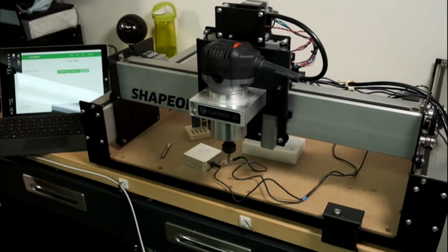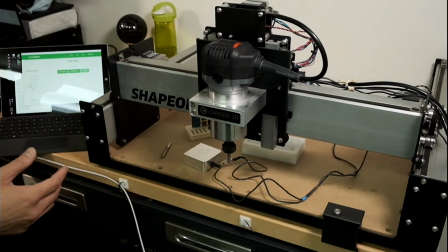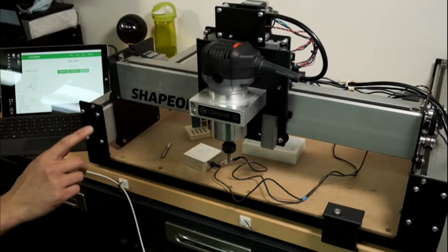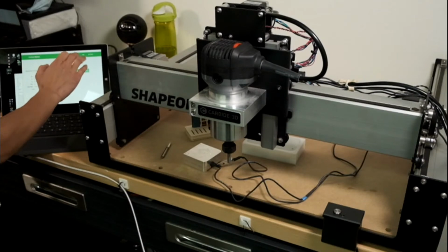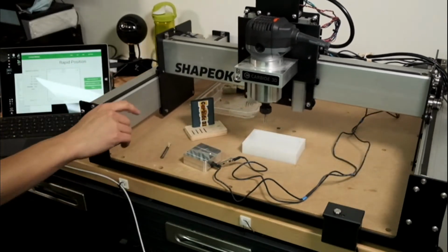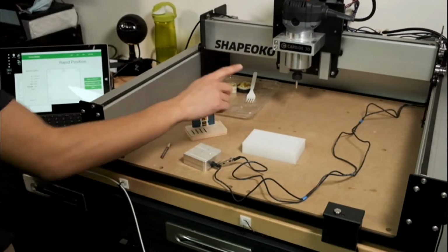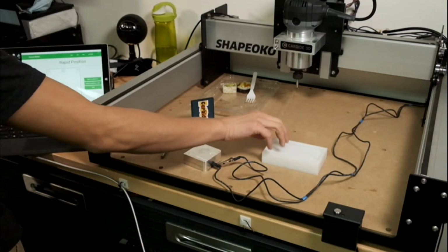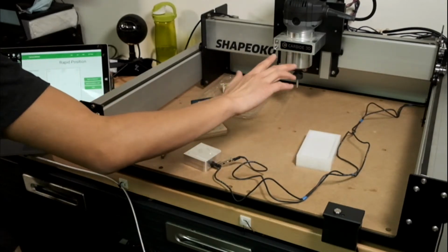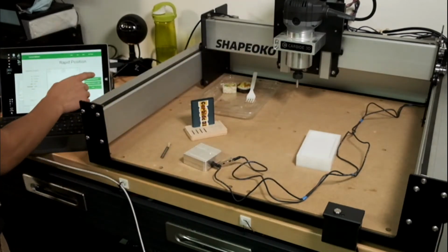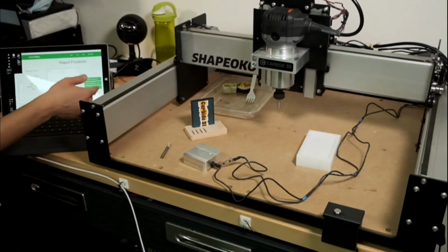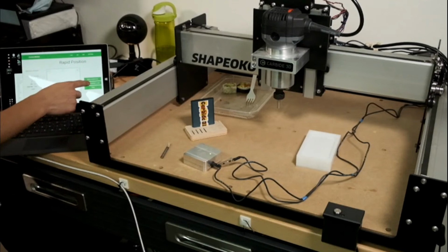So why does it need to touch off a tool after initializing? Whenever you first turn on a machine, the X, Y, and Z coordinates are saved. So if I just jog the machine all the way back, before we start the live stream, I set my 0 in the center, about yay high off the wasteboard. After rehoming, I can wrap it back to the previous X and Y coordinate, because that never changes, so you don't need to find it again, and wrap it down to a Z height.